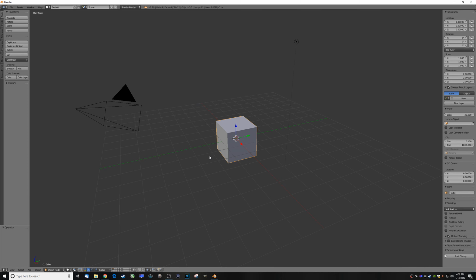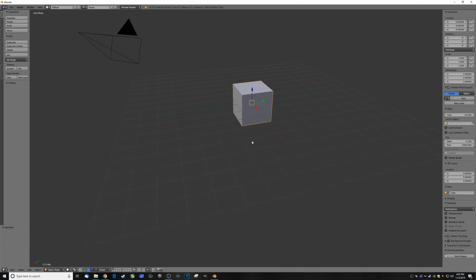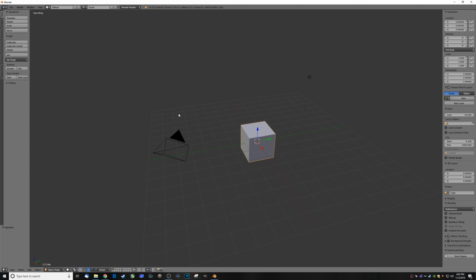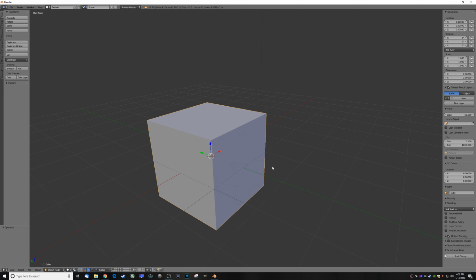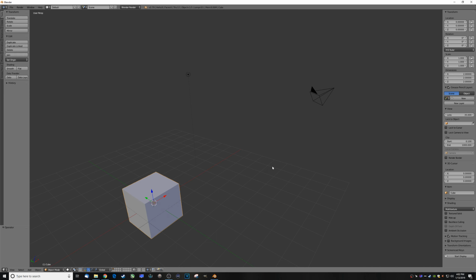To rotate your 3D view with the mouse, use the middle mouse button by clicking and holding and then moving the mouse. If instead you hold down Shift, then you'll pan and move the objects in the scene that way. If you want to make everything visible again, go ahead and press Home on your keyboard and it will make all the objects visible. It will not, however, change the orientation of the axes.